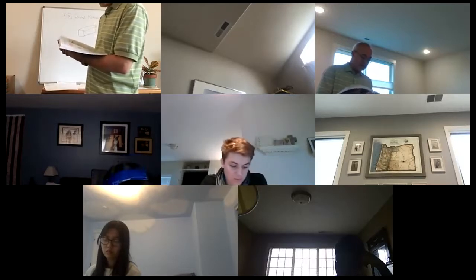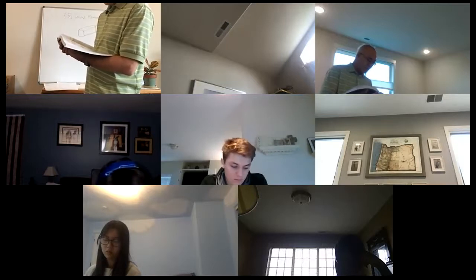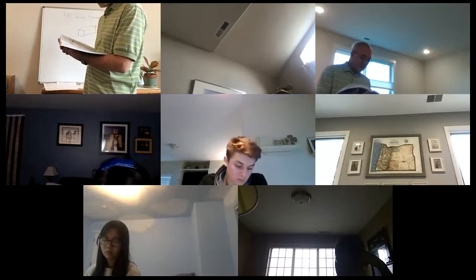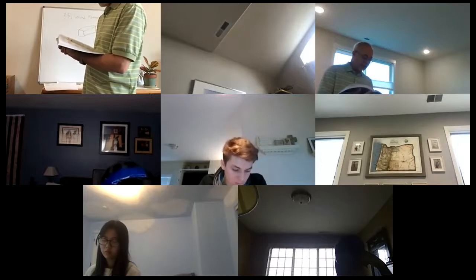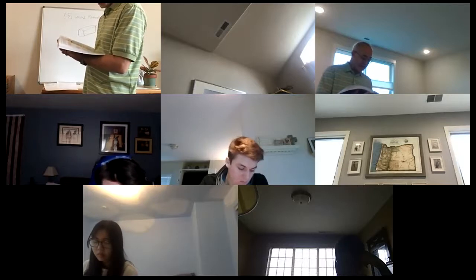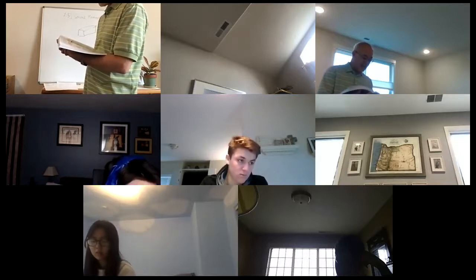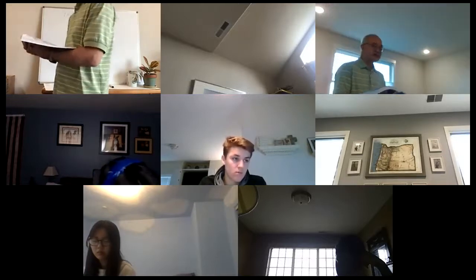So across the X axis, you have width times h cubed, the height cubed, divided by 12. Whereas across the y-axis, the height and the width really just get switched, because you're looking at a different axis.